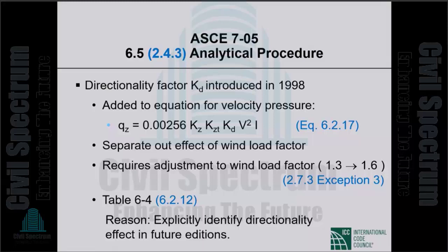Now this directionality thing used to be included in the load factor of 1.3. The load factor of 1.3 was deliberately chosen low because it included directionality of wind.